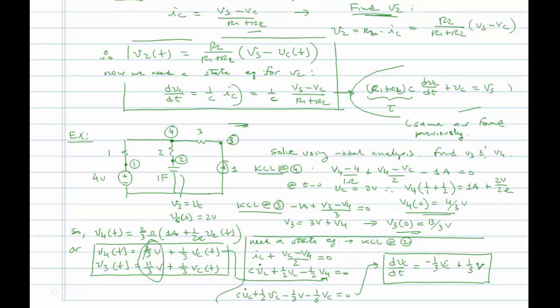Now, note a very important consequence here: if you have a circuit that involves a capacitor, but it has a lot more circuitry than just one resistor, like you see here, there are 3 resistors, 2 independent sources, and then the capacitor. Even so, every single branch current and every single node voltage, or branch element voltage, all of these currents and voltages change at the same rate that the capacitor voltage changes at. So that's comforting to know: if you can solve the state equation and you find that this thing has an exponential decay with a time constant of, say, 10 seconds, then all the currents and voltages in that circuit are going to change at that same rate. They'll have the same form.